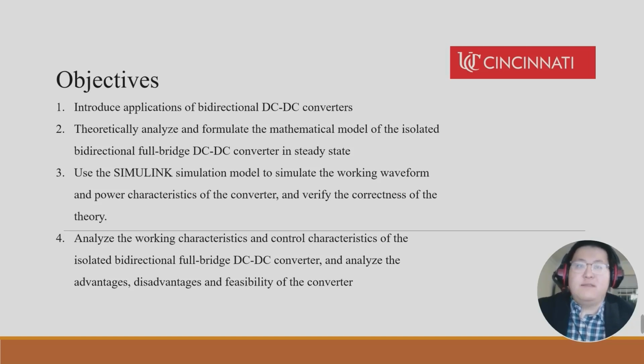full-bridge DC-DC converter in steady state. We use the Simulink simulation model to simulate the working waveform and power characteristics of the converter and verify the correctness of the theory. At last, we analyze the working characteristics and control characteristics of the isolated bidirectional full-bridge DC-DC converter and analyze the advantages, disadvantages, and feasibility of the converter.